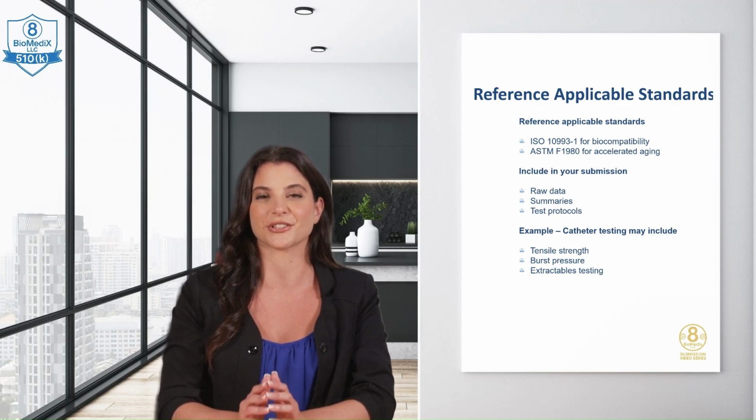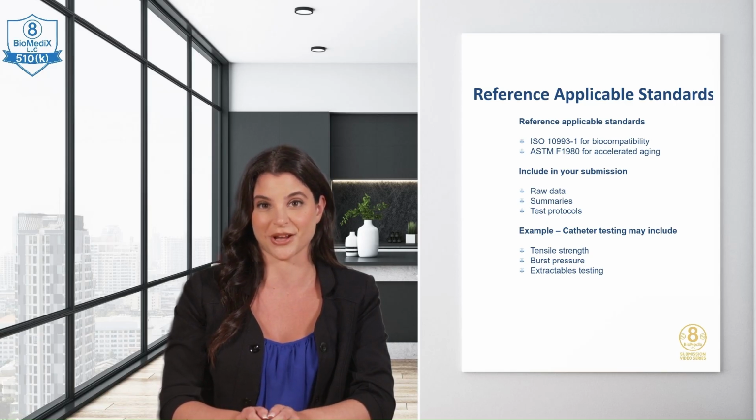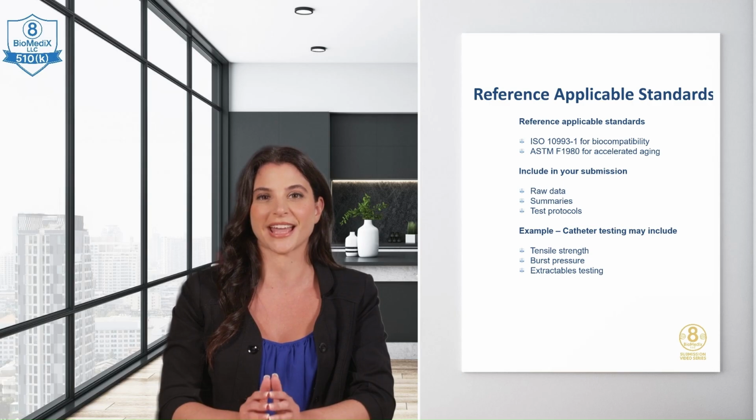Reference relevant standards where applicable, such as ISO 10993-1 for biocompatibility or ASTM F1980 for accelerated aging. Include raw data, summaries, and protocols in your submission. A catheter, for example, might need tensile strength, burst pressure, and extractables testing.